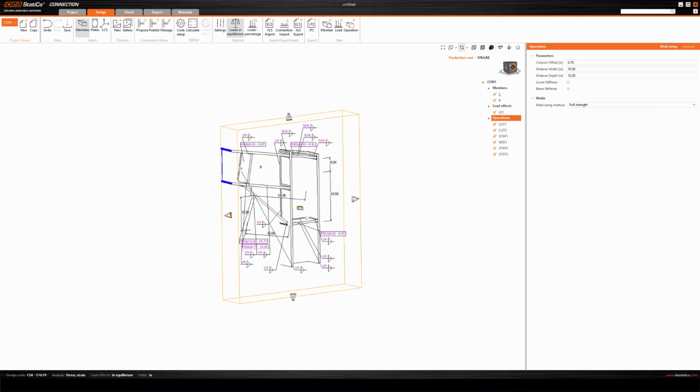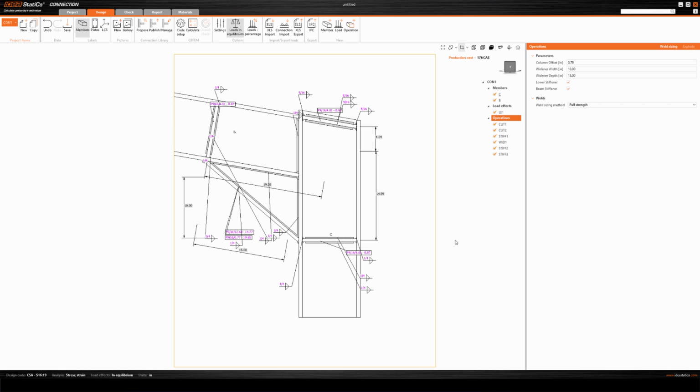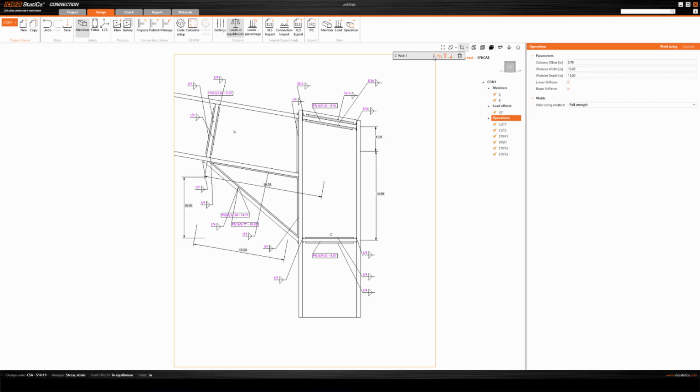So you can go to the 2D view as you see here. And the other option that we can use here, again, it's a new feature, is that you can actually remove or add extra details from your drawing. Okay, so for example, if I drop this down, you will see that here I have control on removing or adding the dimensions from the drawing. You can remove or add the plate dimensions and plate annotations.